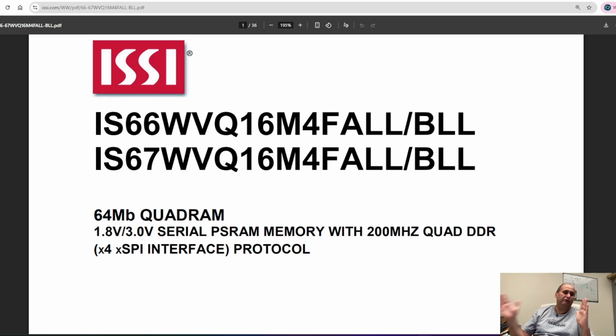Now reading is very frequent in video memory. Writing is not that frequent. Writing is the computer side, which is writing some things in the video memory. So it's not going to happen with the same cadence. So when you make a controller, it will actually have 2 access ports. A video controller, sorry. A controller to access RAM for a video application. You have 2 ports, a reading and a writing port.